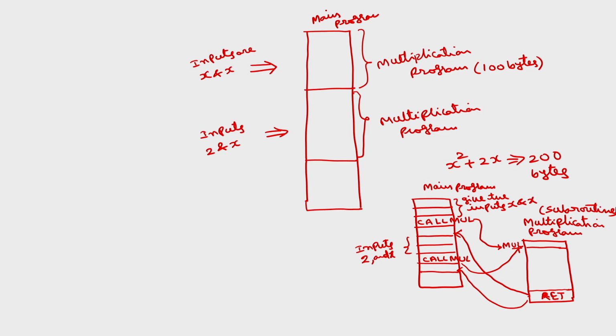But here the problem is, whenever the microprocessor is executing this call instruction, the instruction which is to be executed next is this. The instruction pointer will hold some address. Suppose the offset of this particular memory location is 6000H, so the instruction pointer holds this 6000H. If I do not save the instruction pointer contents and I go to this subroutine, while returning, how does the microprocessor know that it has to return back to this 6000H? So, that is why this 6000 location has to be stored in some temporary location which is called the stack.